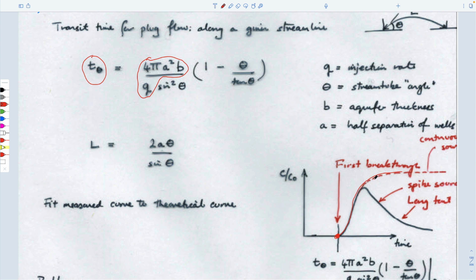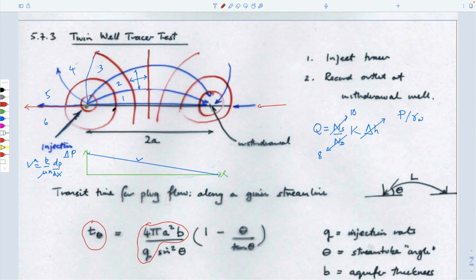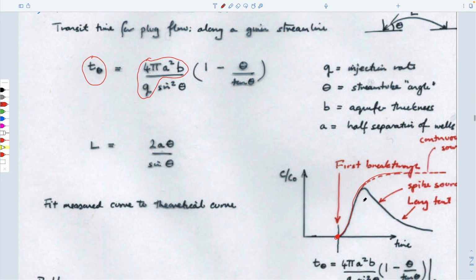It's saying everything about dispersion due to this flow path, which is non-homogeneous. It's fast flow here, progressively slower as each of these goes out, and this artificial dispersion due to the flow regime is manifest in this, even if it's perfect plug flow in each of the flow channels.